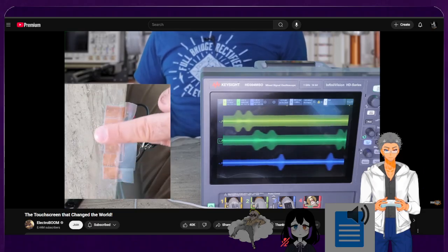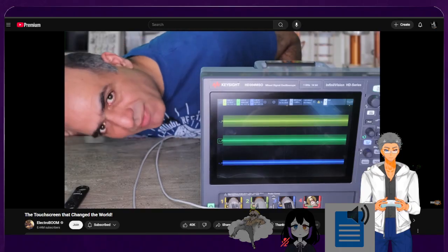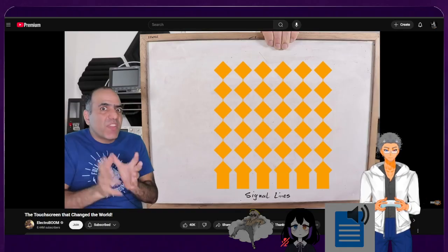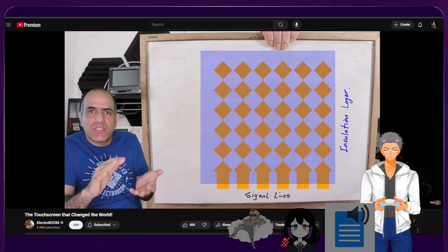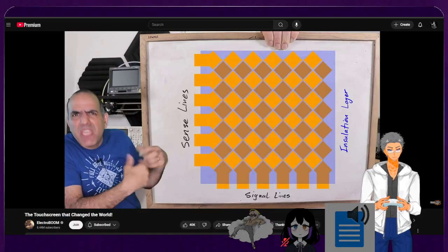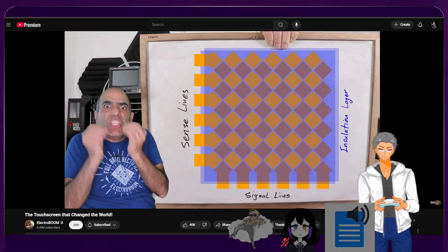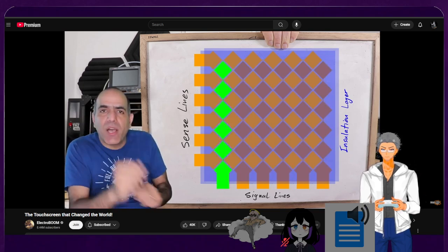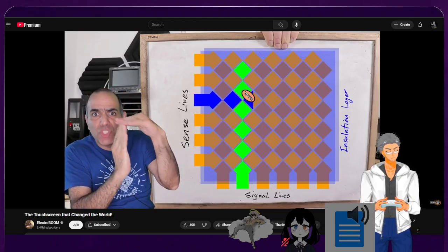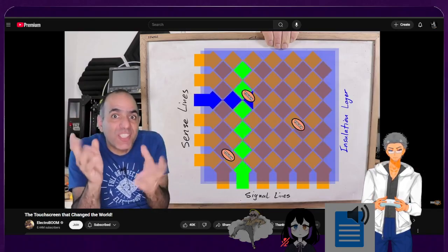Now to turn it into 2D, it's a bit more complex. It's a multi-touch sensor after all. Typically, they extend the signal lines over the screen in a specific shape. Put an insulator layer on top, and with a similar shape, they run the output lines horizontally with minimal overlap between the two. And then there is another insulating layer on top. Then they turn the signal lines on, one at a time, and look at the output. Depending on which signal line is on and which output shows changes, they understand where you're touching. This can also detect multiple touches at the same time.